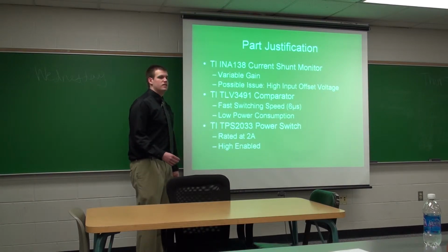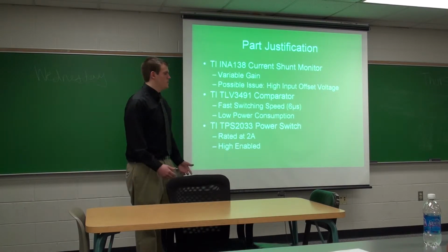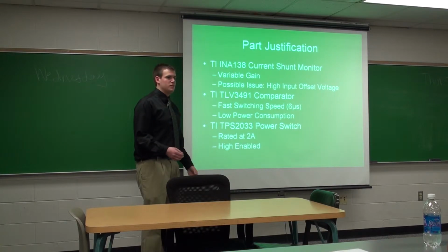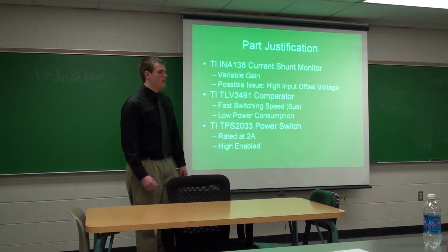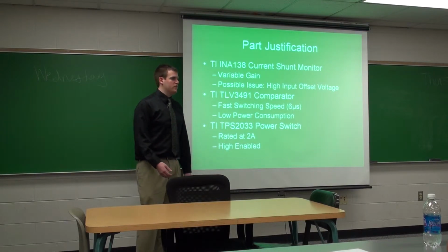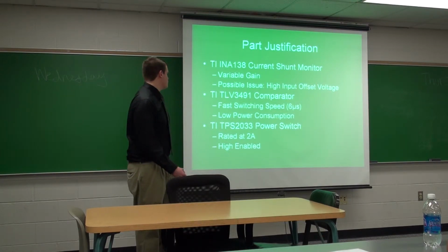Next is the TLV3491 comparator. The reason we chose this is because of its fast shutoff speed, it's 6 microseconds, and it has very low power consumption. It takes microamps for it to be powered up.